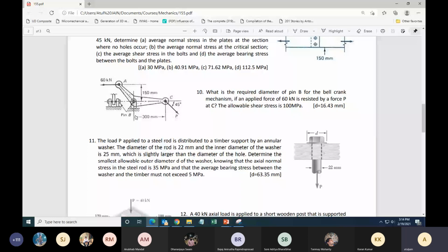The magnitude of the force is what matters, the direction doesn't matter, as long as it is parallel to the circular cross section. I think this problem is given to ensure that you understand what double pin shear is, and that you have to take the magnitude of force, not only Bx or By. Please try question number 10.